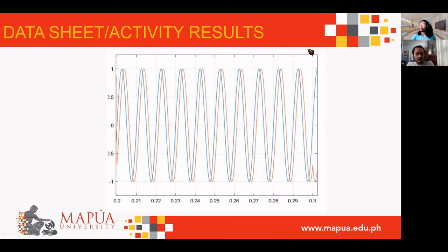So lastly, at 0.3 seconds, the MSB has already finished its half cycle again, which is why it comes back to 0, while the LSB has not yet finished its first cycle, which is why it is still at 0. Therefore, the last 2-bit code of the pattern is 00.